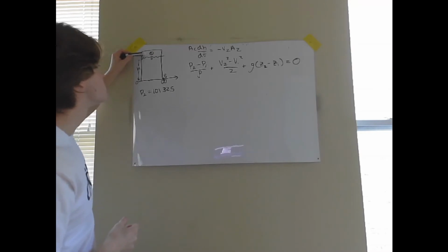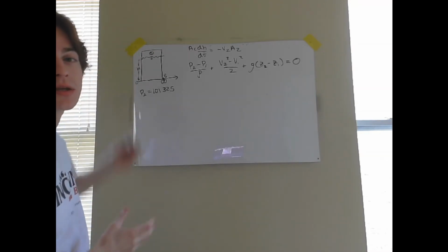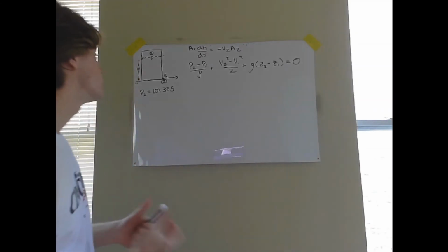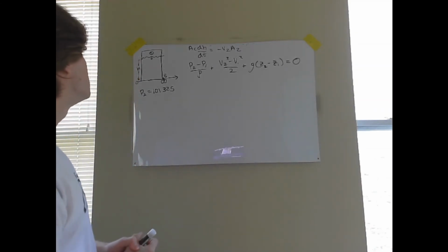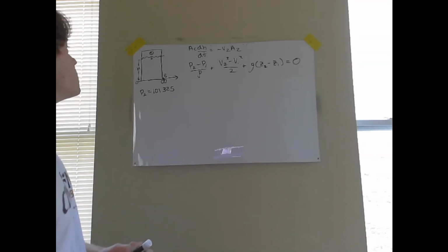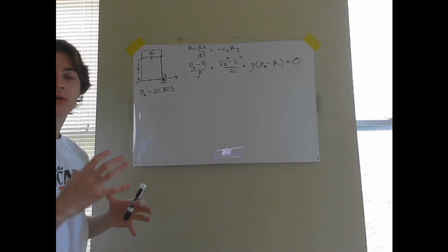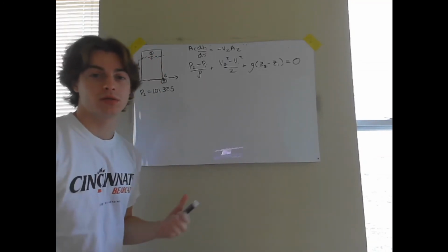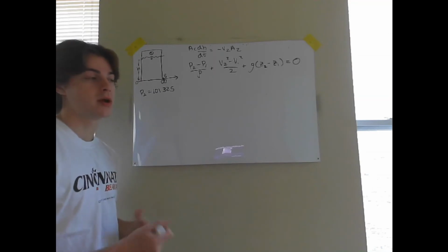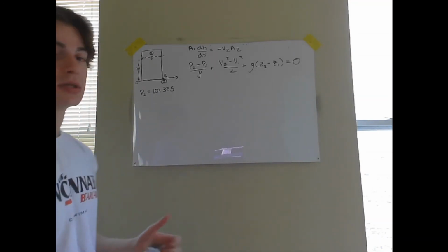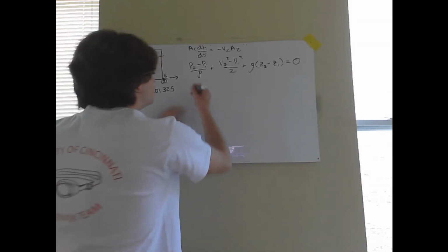But now that we've closed the top of the tank, this air pressure is going to be changing as we drain the tank, because the volume is going to be increasing, but we have a set amount of air in there. So we have to find a way to represent that. To start, we need to find the moles of air that's in the top of the tank. Since it's sealed, there's no air leaving or entering the top of the tank, so we can use the initial conditions to get the set amount of moles for this problem.